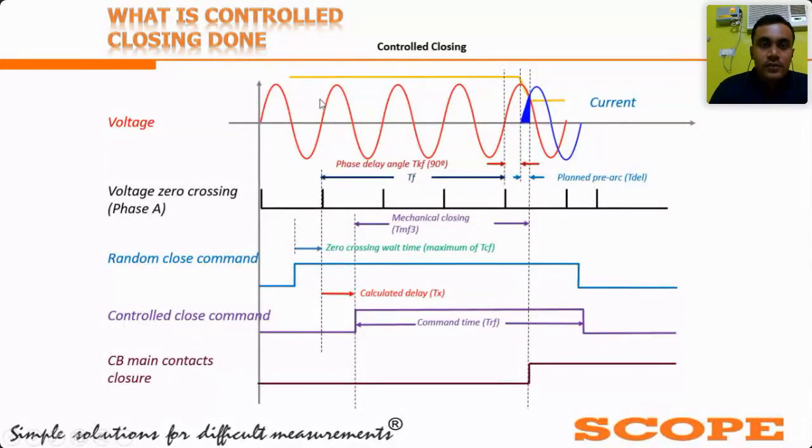generally our CSD relay takes bus voltage as a reference, because from the start we provide it to the relay as an input. So our CSD has the feature that we can synchronize it at falling edge, rising edge, or alternate edge, depending upon the different site situation.